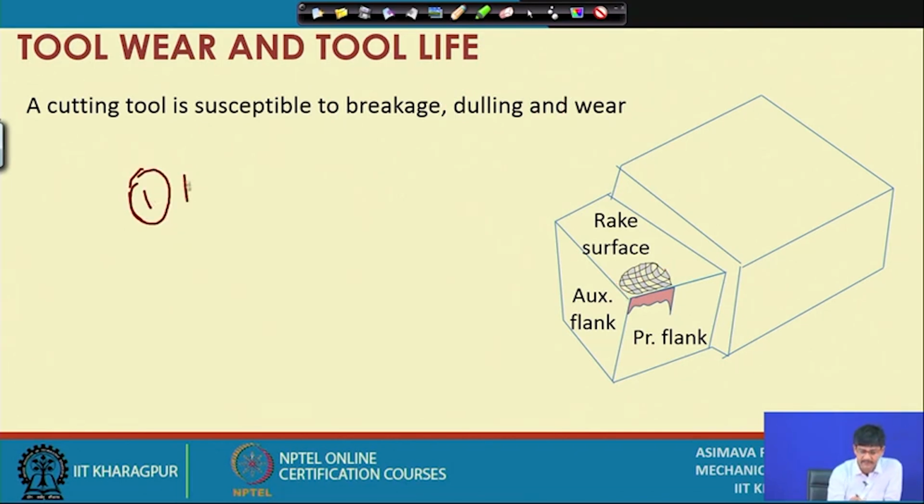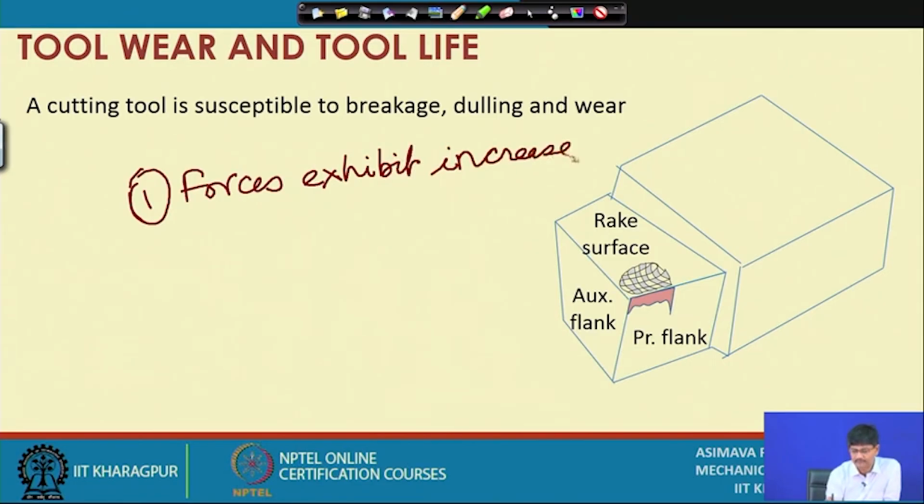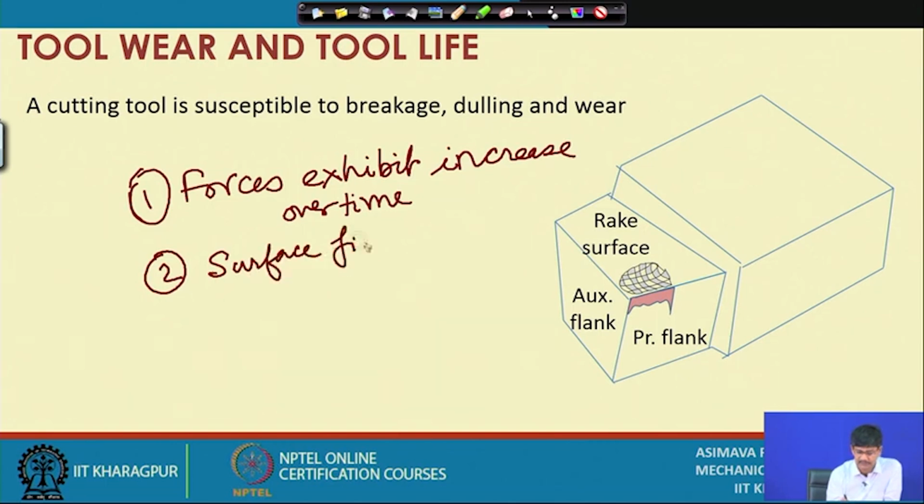These are the indications: forces exhibit increase over time. Then other things might also happen. Suddenly you find the surface finish which is obtained on the workpiece is not acceptable, it is deteriorating.